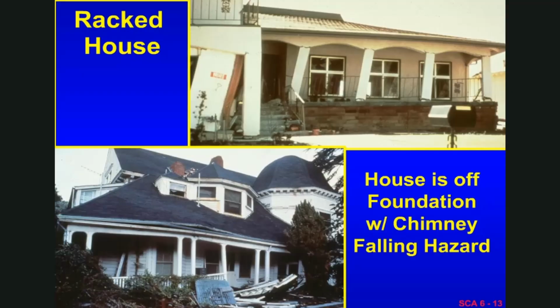The other thing that one needs to know about these structures, that once they've come off their foundation or shifted, is that they would contain very badly sloped and broken floors with pieces of wood sticking up and nails sticking out and all kinds of tripping and falling hazards and perhaps broken wires and the potential for electrocution. And so, again, all those things need to be handled before you enter the structure.